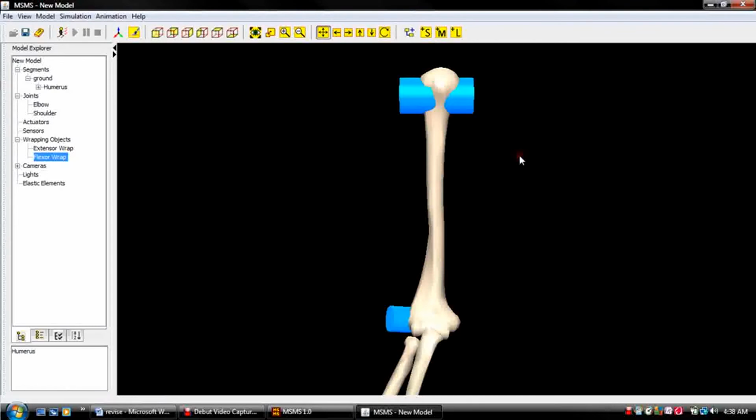Okay, so we're going to go and click on the 3D window, select the object, and continue moving it down. So I'm going to click Shift and Y button. We're going to move it all the way down to negative 0.12. And now we're going to click Shift and we're going to hold on Z until it is negative 0.014 meters.